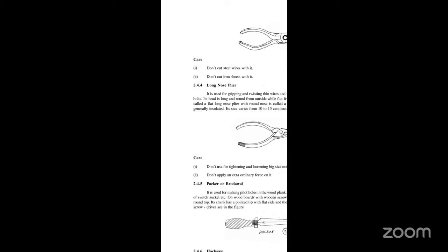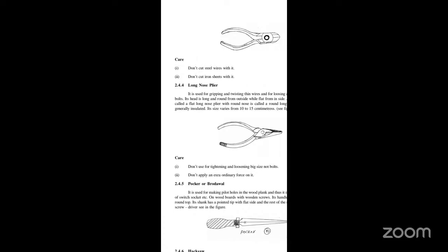Next, what are the uses and what care is required for this? Don't cut steel wires with it. Don't cut iron sheets with it. So iron sheets and steel wires can't be cut using this instrument. Now, long nose plier.